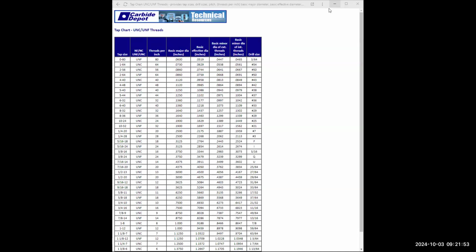Now I'm going to copy CP, enter, select the text, enter, indicate, click, drag down, click, enter. Now we need to edit this. DD edit, enter, click on the text, enter. And we're going to type this. This is a counter bore. Percent C 0.75 space deep 0.25. Enter. Click anywhere on the screen.